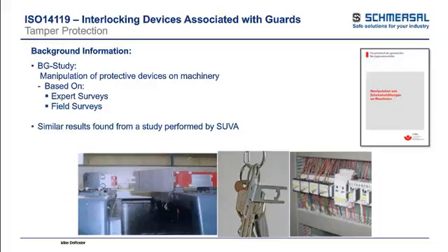Or the ever so common having a spare actuator on a set of keys, as you see in the middle picture, and even to the extreme where people have found contactors. I know it might be a little hard to see on the screen, but if you look closely in the center of the contactor, that's basically either screws or nails that have permanently held that contactor on to keep power on that unit, which is obviously a huge no-no.